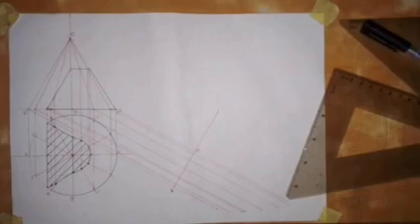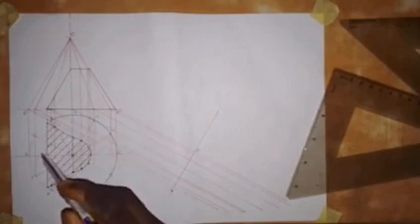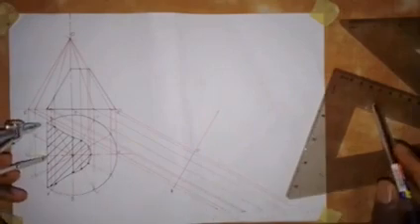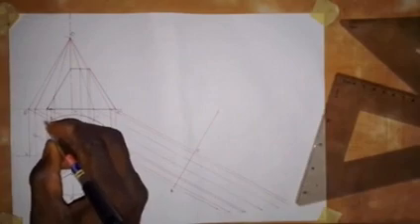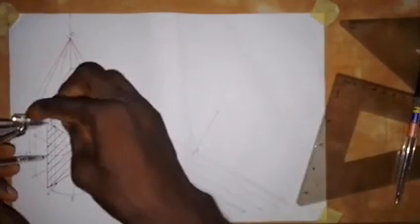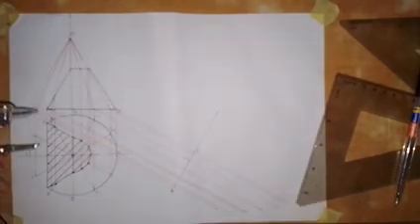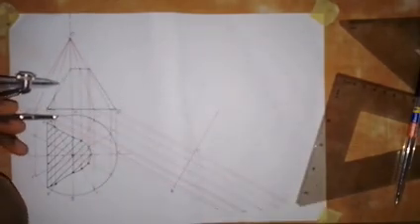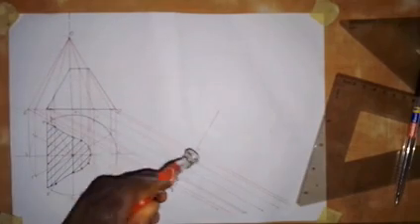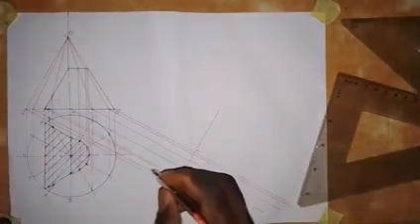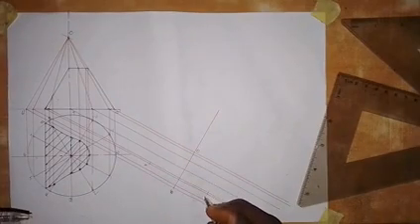What we are going to do now is take your compass, as I've taken my compass here. This is the vertical line that we produced down here, and the midpoint is here on 0.6. Put the compass at the midpoint and take this distance from this point here. If I call this point A, take the distance from the midpoint to A. Then follow the line that we produced from this point here, and come to the center here. Make an arc on this side for A, and also make an arc on this side. So this is point A, and this is also point A there.